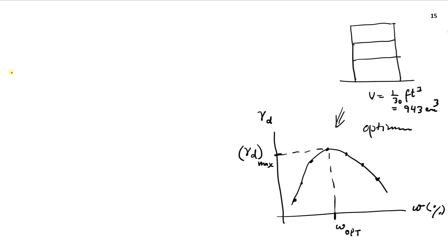Okay, so one more thing is, we know that the dry unit weight is equal to this formula, Gs gamma w over 1 plus e. We derived this formula in the chapter on phase relationships, and also the void ratio e is equal to w Gs over S, where S is the degree of saturation and small w is the water content.